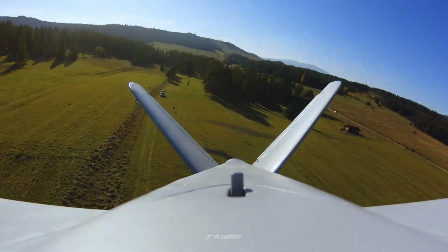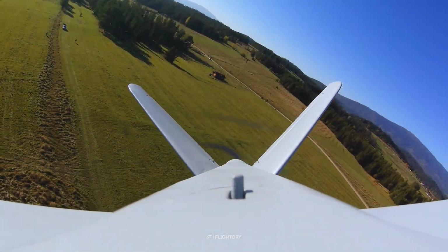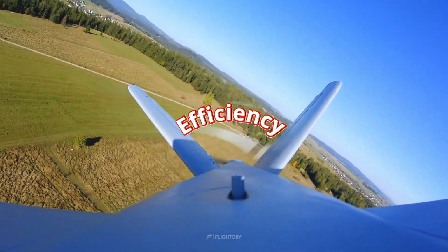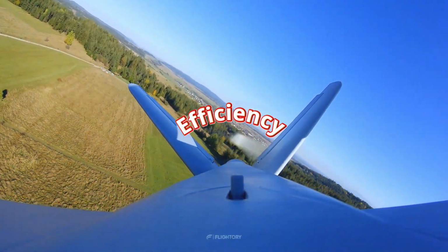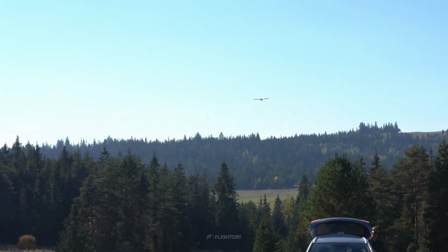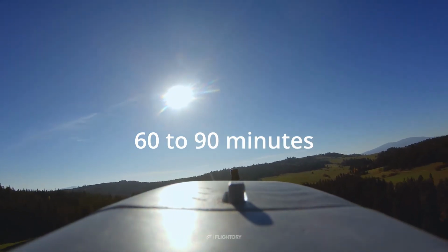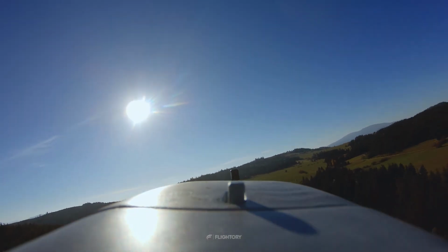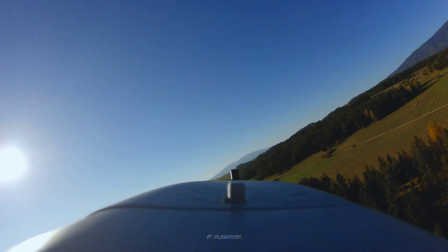Now why would anyone design a drone this way when we have quadcopters that can hover? Because of efficiency. When your wings are doing the work of holding you up, you're not constantly fighting gravity with motor thrust. You can glide, you can cruise. This means you can stay in the air for hours. We're talking 60 to 90 minutes, even more so for some professional models. Compare that to a quadcopter, 20 to 40 minutes tops.